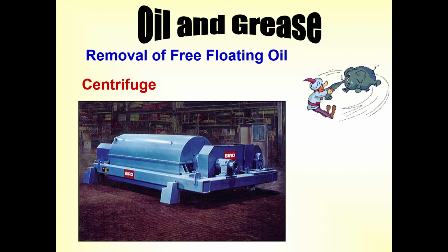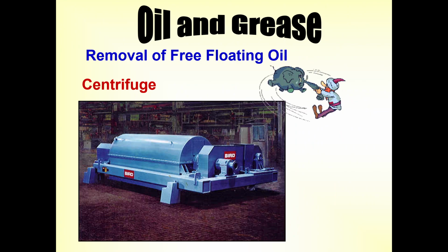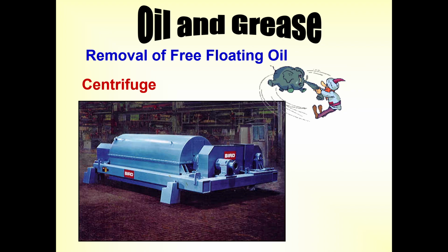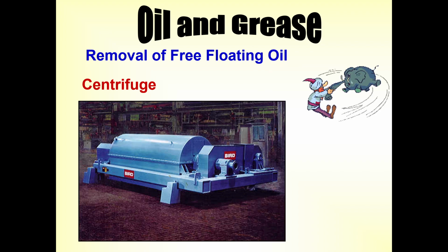When it is rotating, the grease will be removed from the exhausted air by using the centrifugal force. The hoods will have a centrifugal bowl or centrifugal spin the oils, with the particulate settling out on the inside wall. A layer of water forms on top, with particles, and an emulsion will also be formed.